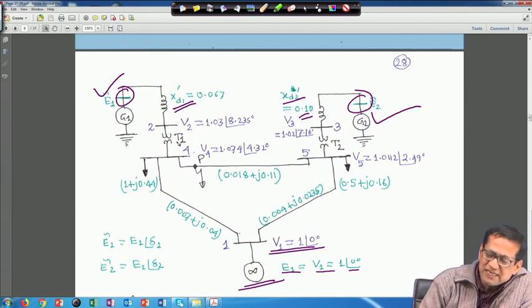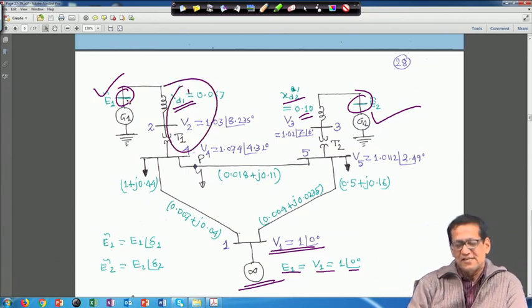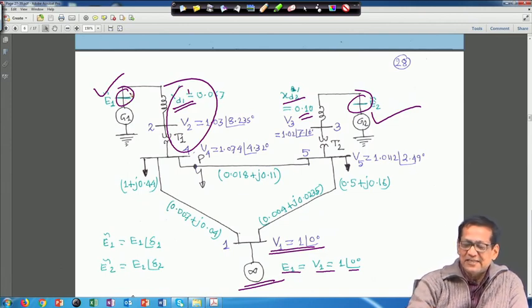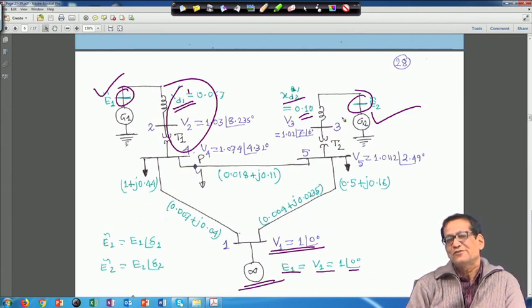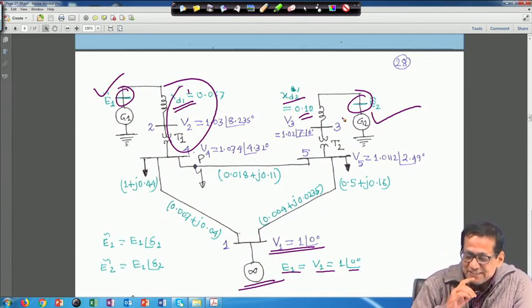That means, whatever transformer reactance there is, you have to add it to these two reactances and then find out the admittances. So, that will be your y 22. So, you need not consider this one and this one as another bus. No need, right, no need. That is one thing, but in the previous example there was no transformer.